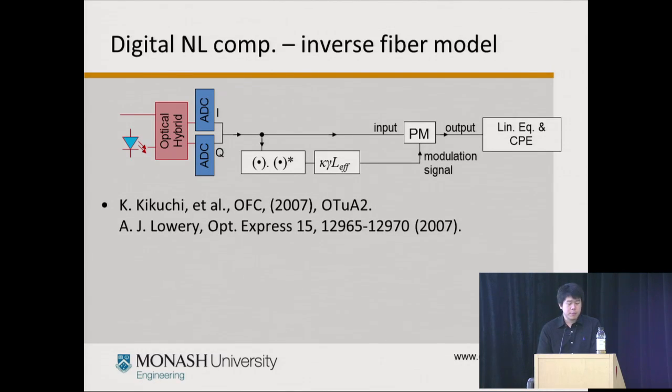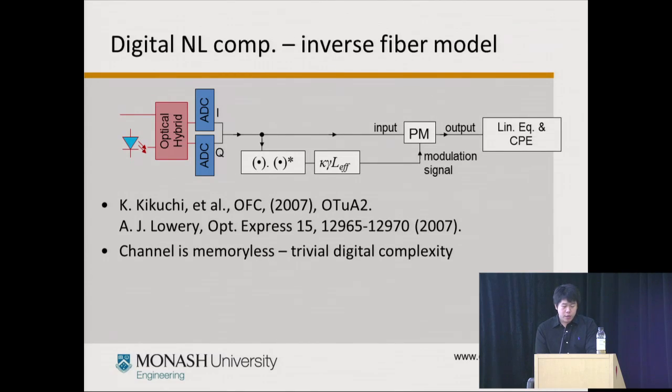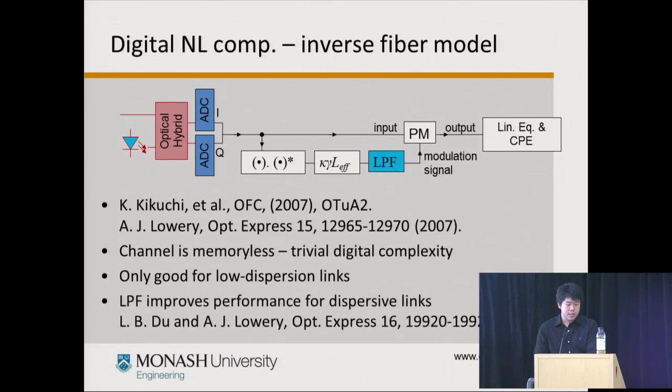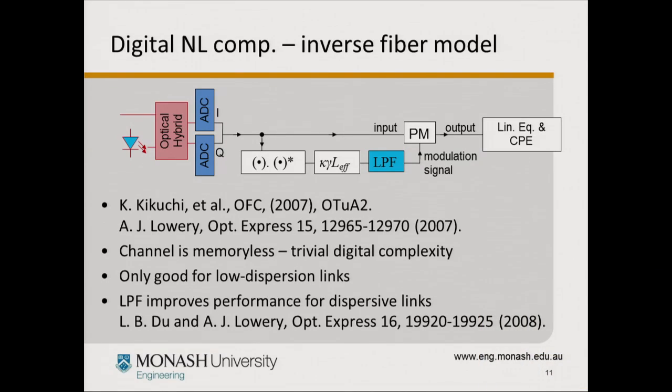This method was first proposed by Professor Kikuchi and by Arthur Lowery. Now, because the channel is memoryless, the computational complexity is very, very low, and it's trivial compared to the linear equalizers that are already used in these coherent systems. Just like before, it's only good for low dispersion links. And later on, we showed that by placing a low-pass filter here, that improves the performance of these single-step methods.